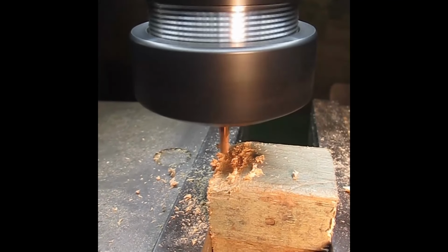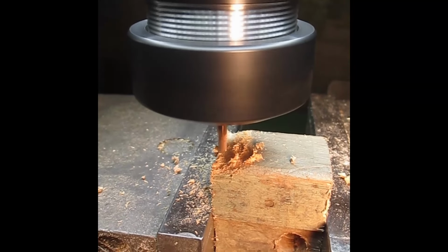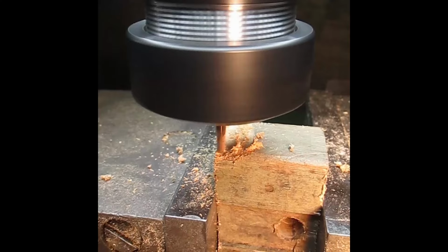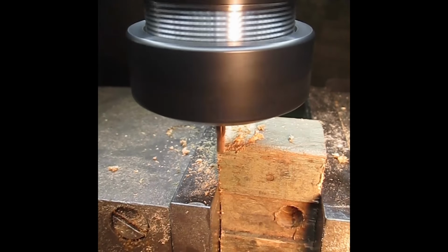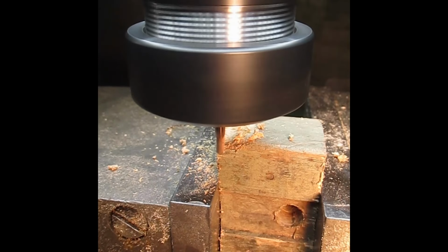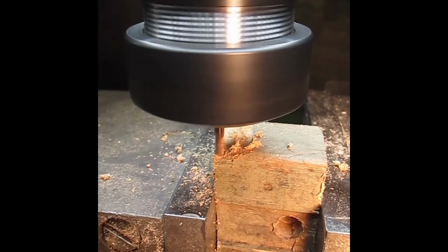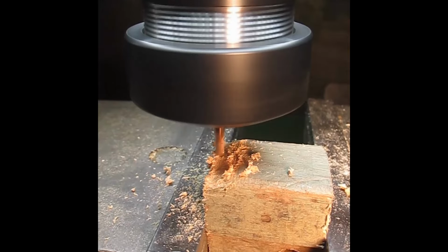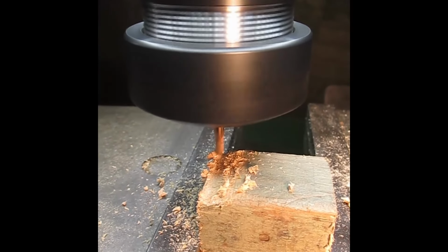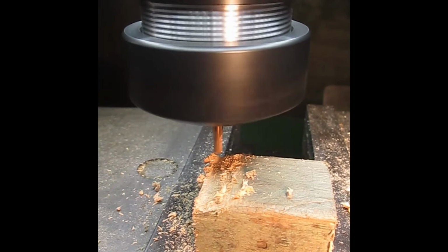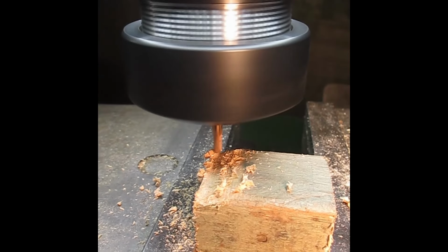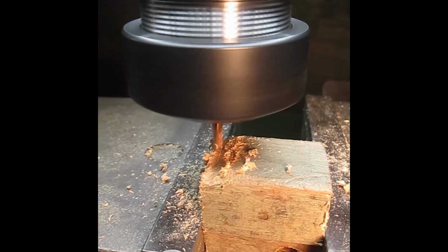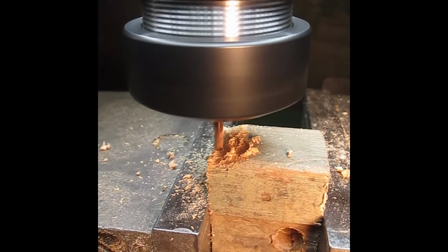You'll have noticed that there are scallop lines from the cutter visible on the new face. The desired slope line actually touches all those scallops tangentially, so afterwards I can take them off and linish it, and when the scallops disappear I'll be on the desired slope line.